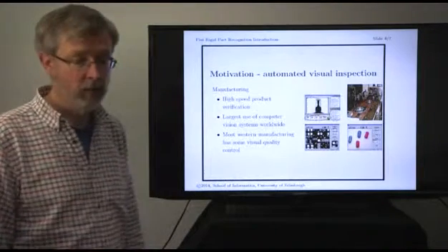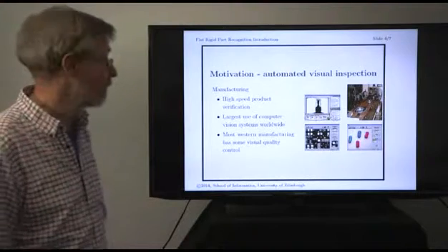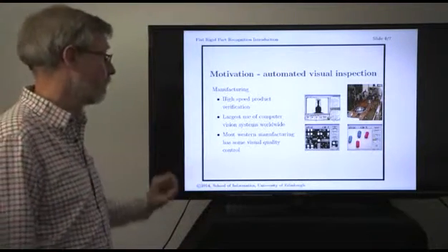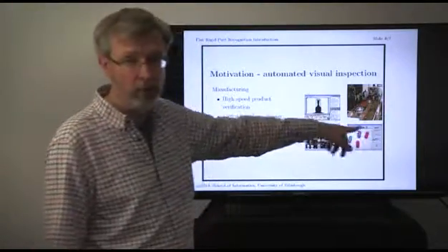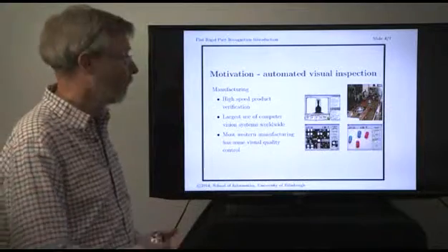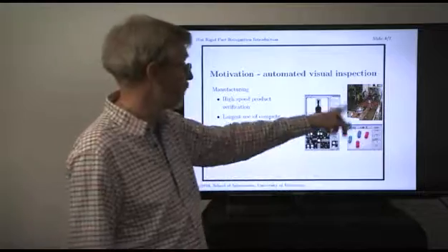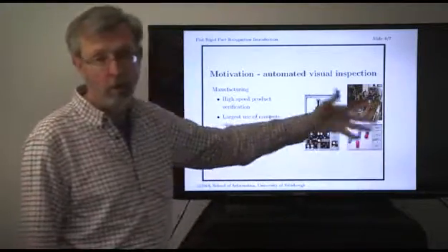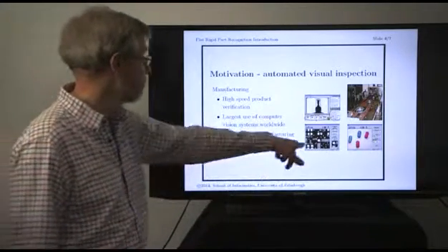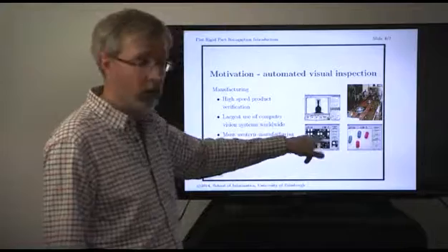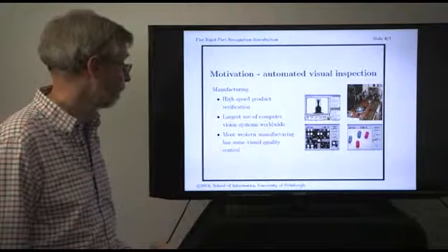Well, why do we want to do this? Well, a lot of computer vision in the factory area is all based around these sort of simple object recognitions. You've got objects that come down on conveyor belts and maybe in different positions, different orientations. We want to be able to identify where the parts are on the conveyor belts. We want to be able to maybe do some inspection of the part to make sure whether the features have been properly formed. We want to be able to estimate positions, for example, on circuit boards if we're going to insert components into that circuit board or drill holes or do some soldering.